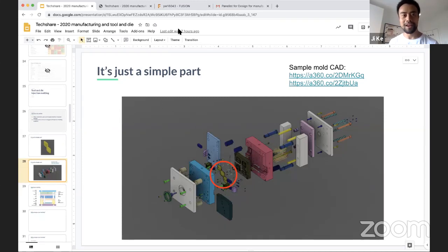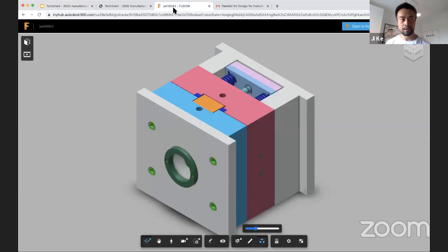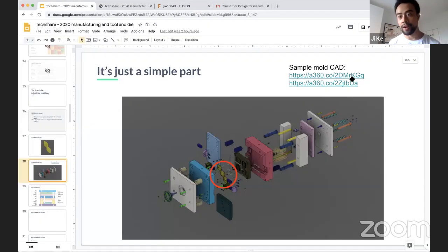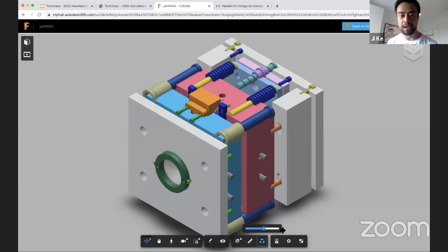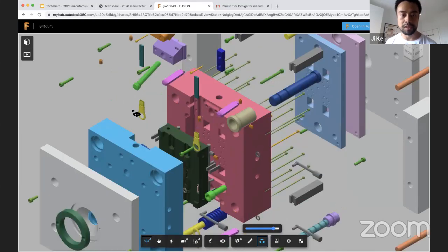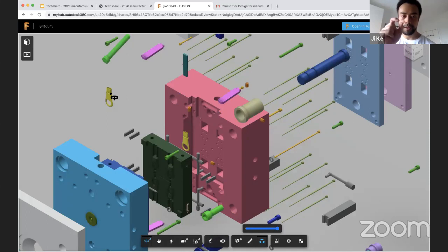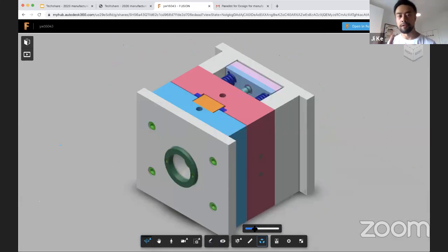All right, cool. I actually do have a CAD drawing, and these are public files. These are tools for some of my designs, and you can download it, play around with it, and see how complex these parts are. This is for a USB stick grabber, and even though it's a cavity of 4, you can see how many injection pins, how many glides, how many sliders, and all these kinds of things will contribute to the cost of the mold, right?